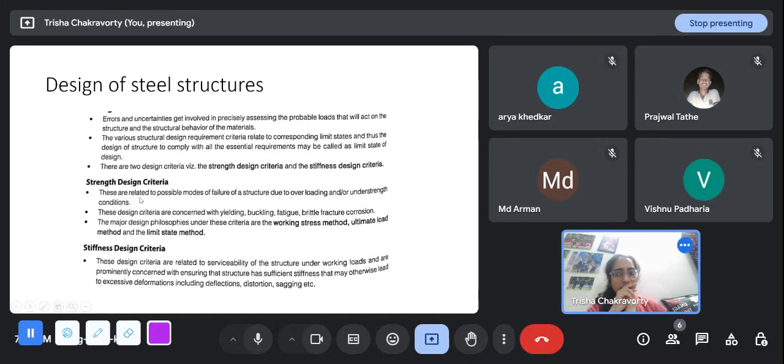These are related to, maybe just in a very simple manner, the stress strain curve we saw. If you plot stress on the y axis and strain on the x axis, the stress strain curve goes in a vertically upward direction, and the slope is the Young's modulus. So force or stress, denoted by sigma, is the y-axis quantity, and the Young's modulus is the stiffness term here. Young's modulus is stiffness in case of tension. Then there is a shear modulus, there is a bulk modulus. All those are stiffness terms.